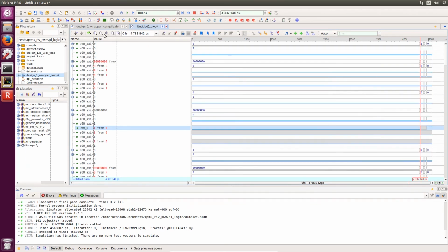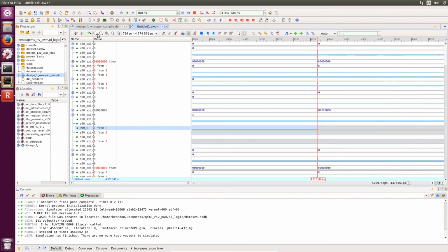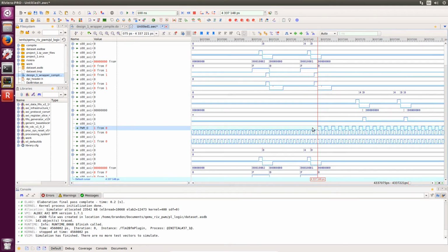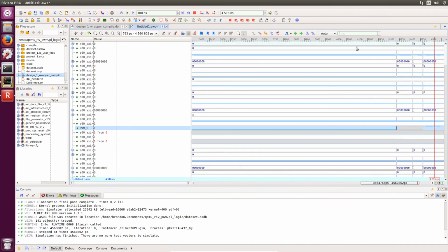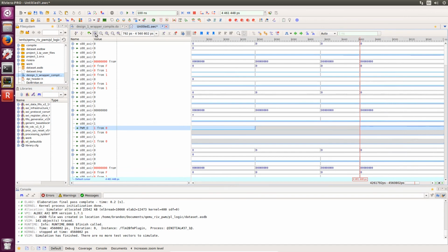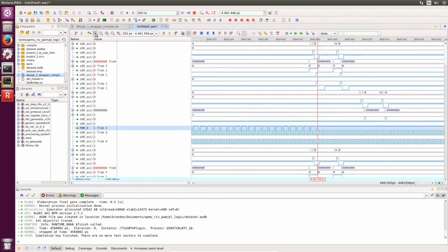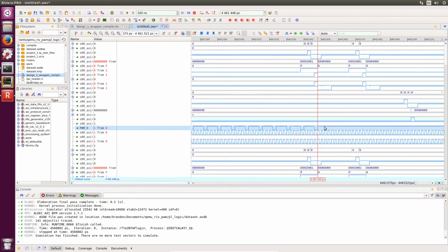Zooming into the time we initiated the emulator, we can see how the output signal reacts to what was provided from the software side. Our signal started at a 0% duty cycle and was changed to a 50% duty cycle. Zooming out and navigating to another transaction, we can see that final transformation of the output signal from a 75% duty cycle to a complete 100% duty cycle.